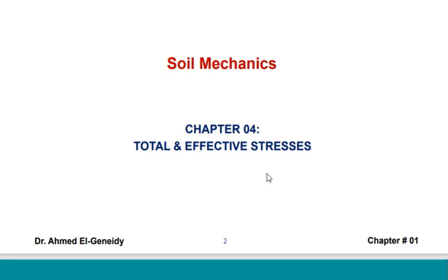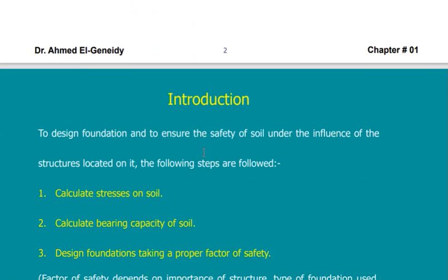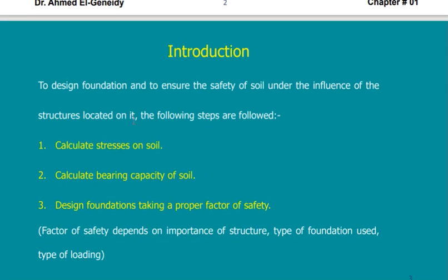So what will happen is that I will stand on the clay. Part of my load will go to the water and part of my load will go to the clay. So nothing will happen immediately. The water will carry a considerable part. But as time passes, water starts to consolidate or to seep outside. So when water goes outside, my load is going to be transferred to the clay, and the clay starts to be compressed more. So this is our introduction for this.